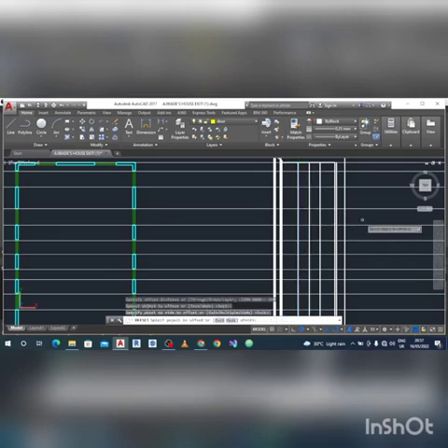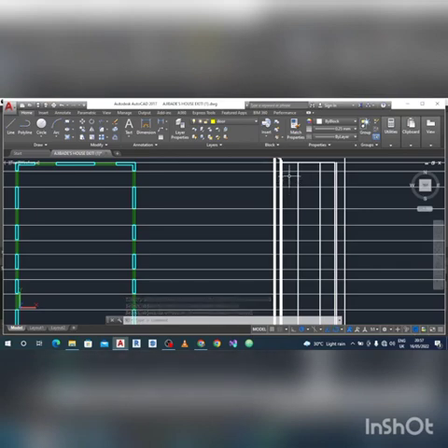Whenever we have a toilet window, some toilet window heights are 600, some are 900, depending. So don't let us get confused. Or better still, let me just exit that. Let us take out the main windows, then we'll focus on the toilet windows. So we introduce our trim tool, that's TR, enter, enter.